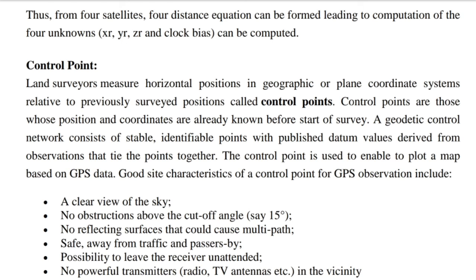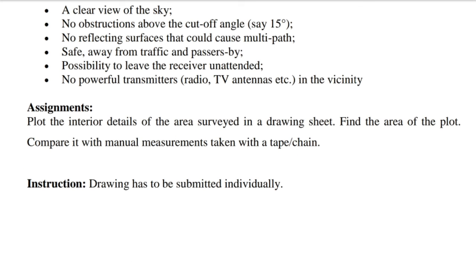in the vicinity. Assignments. Plot the interior details of the area surveyed on a drawing sheet. Find the area of the plot. Compare it with manual measurements taken with a tape or chain.